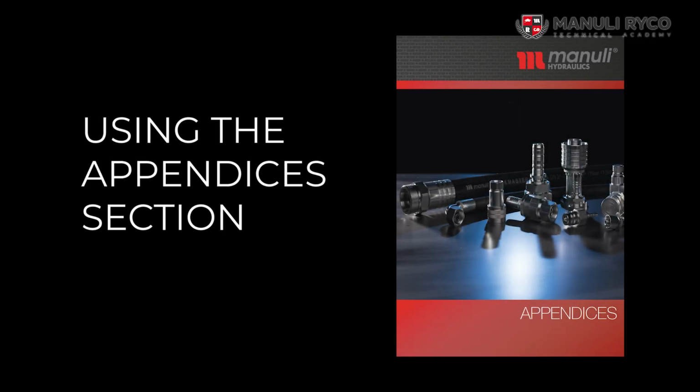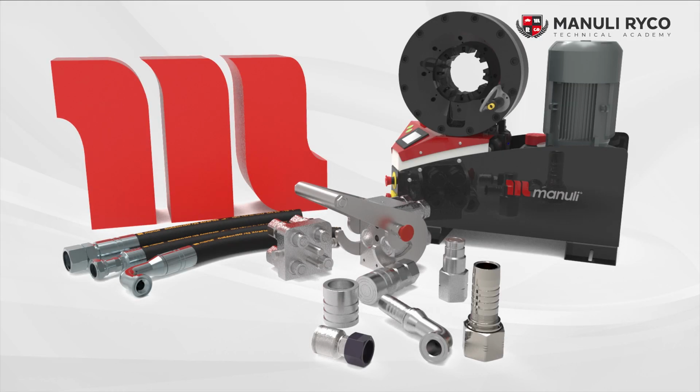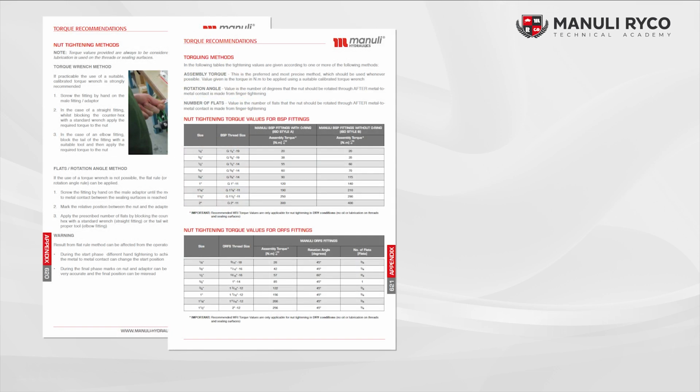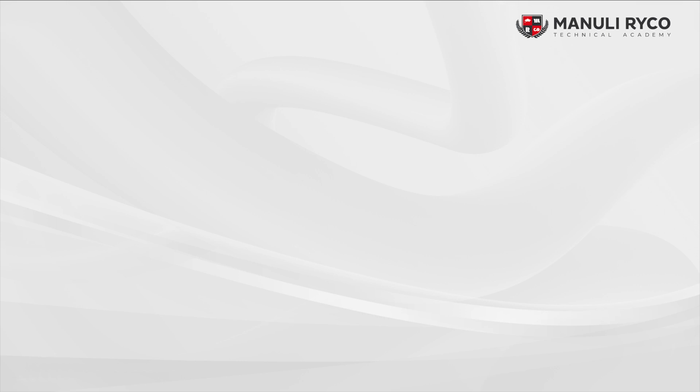Using the Appendices section. The final chapter in the catalogue is the Appendices section. This section contains important information for using the catalogue and for the selection and use of Manuli Hydraulics products. The first few sections deal with basic understanding of terminology, symbols and hose sizes used throughout the catalogue, and it is important that users read and understand these pages. The next section deals with torque tightening for the various termination end types. It is critical that correct torquing of fittings is done to ensure safe, leak-free installation of Manuli hose assemblies.